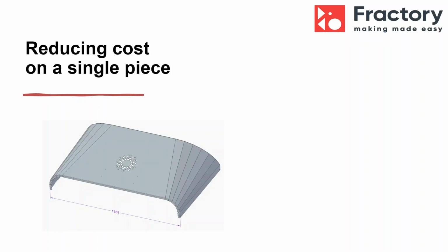Now, I've got a couple of examples of folded components, and where typically we try to save some money and reduce some costs. We've got this lovely piece here, which has tabs all the way around the bottom. That's the same on the other end, and this kind of conical form feature, which is made up of lots of bends, which we call step bends, just to be able to give that larger rad and larger angle.